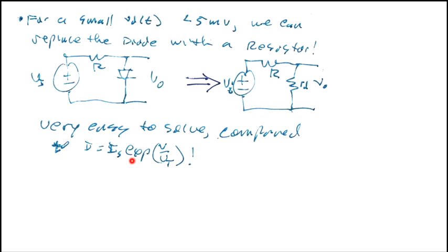The good thing is that inside of almost all our electronics, signals are almost always small. It's much easier because we can linearize circuits using this kind of small signal approximation. It actually means that a circuit is linear for very small signals. So almost all the signals in a circuit that aren't digital are very small signals, a few millivolts, microvolts, like that. And we can use those small signals to make our radio amplifiers and radio receivers and A to Ds and D to As and all those other linear circuits. We can make all those work with small signals.